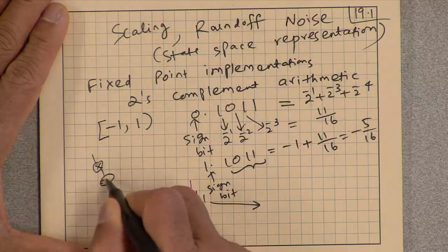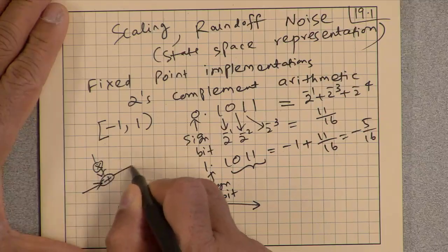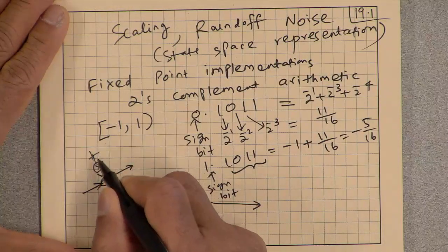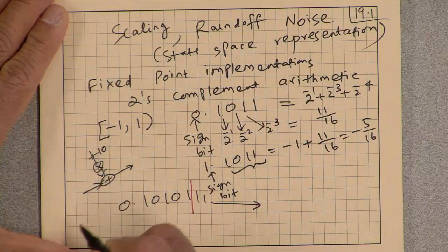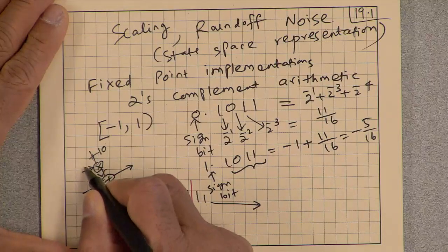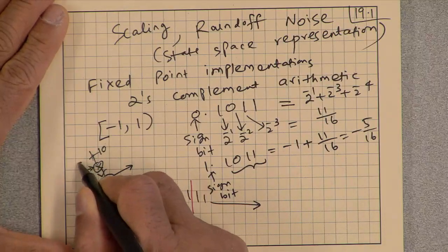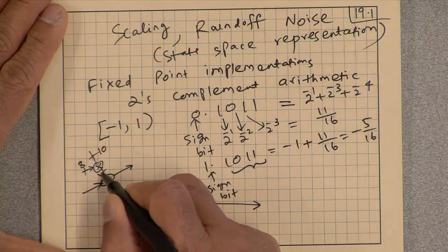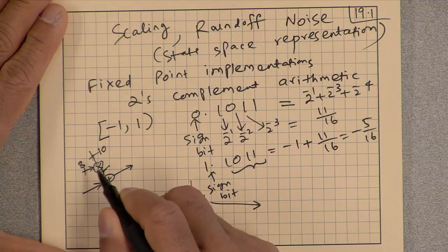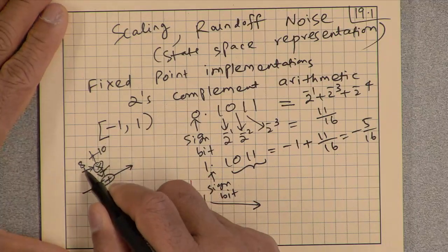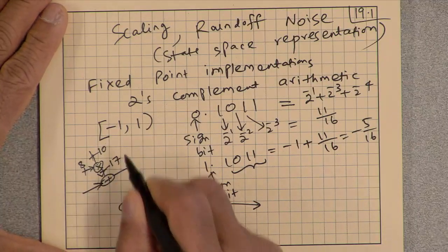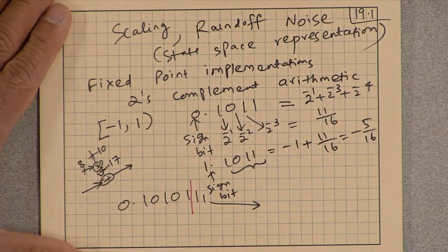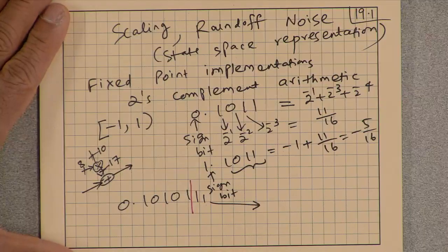We multiply a number and add something to that. For example, if we start with a 10-bit data path and an 8-bit coefficient, the product of 10 bit and 8 bit is like a convolution, right? The convolution of a 10-point sequence with an 8-point sequence is of length 10 plus 8 minus 1, and multiplication in many ways is kind of a convolution in another domain.